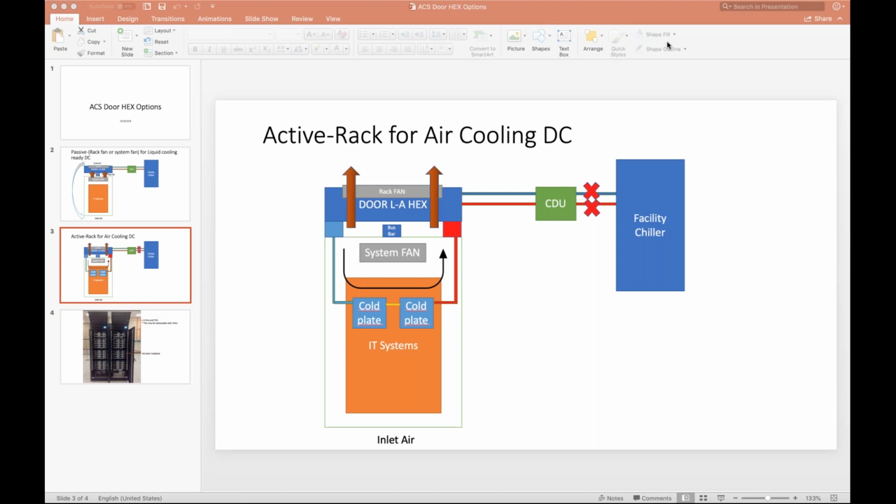This is Martin Dörch from Rittal. So I think I do have the same opinion. We are here mixing up two different solutions. As far as I understand, direct liquid cooling is a topic of another ACS group. So we do have the rear door heat exchanger, and the integrated fans inside the IT systems push the air directly over the big coil integrated in the rear door, what we call a passive rear door.